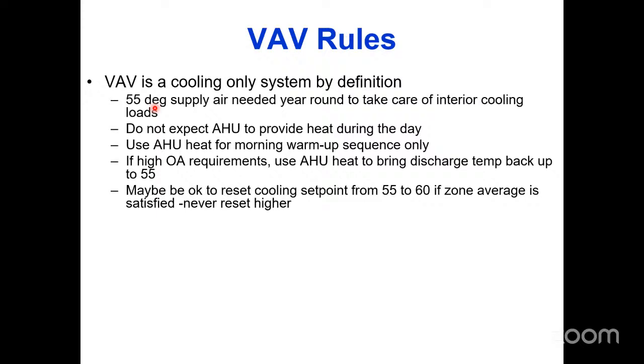All day long, no matter what. It's -3 out. I don't care. Here's your 55-degree air all day long. So that's its job in life. And if zones need heat, great. They can provide their own heaters to do that. Do not expect the air handler to heat during the day. Do not expect the rooftop to heat during the day.